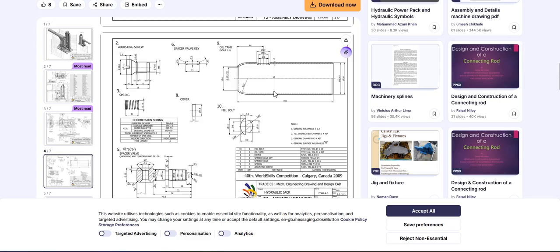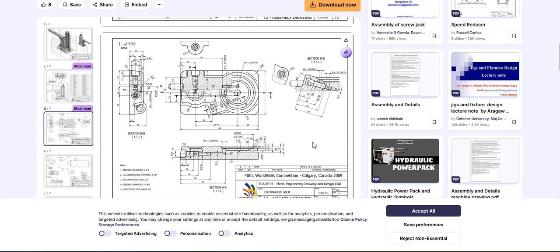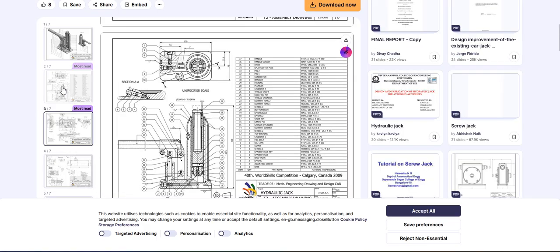If it's a thin sheet like that, it's going to be done by sheet metal working. You can see that the block is going to be made by casting. Usually it's going to be sand casting, because it has these internal details which are usually provided by the sand casting process. And those parts are going to be done by bending different parts of the metal to get the final shape.